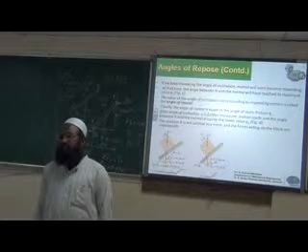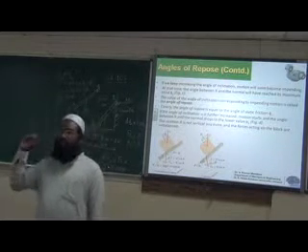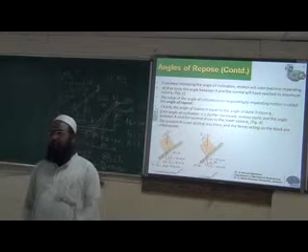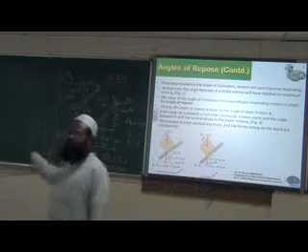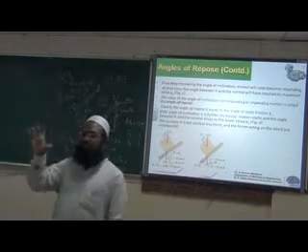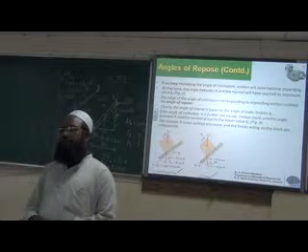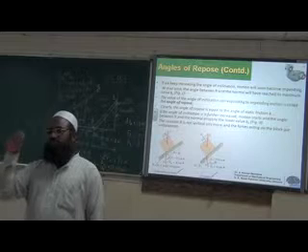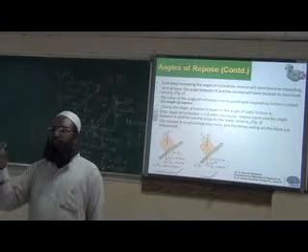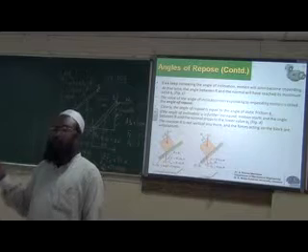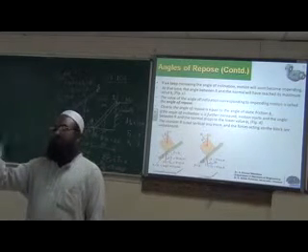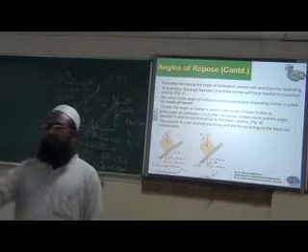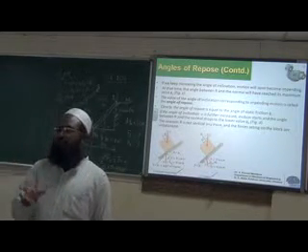So how will you proceed? Following the same steps, we will find the frictional force required for equilibrium. FF is the frictional force required for equilibrium. Then we will find the actual frictional force using the given mu. First we find NF, then FF, then mu is given. So mu times NF will give the maximum friction force we can have for the particular coefficient of friction.